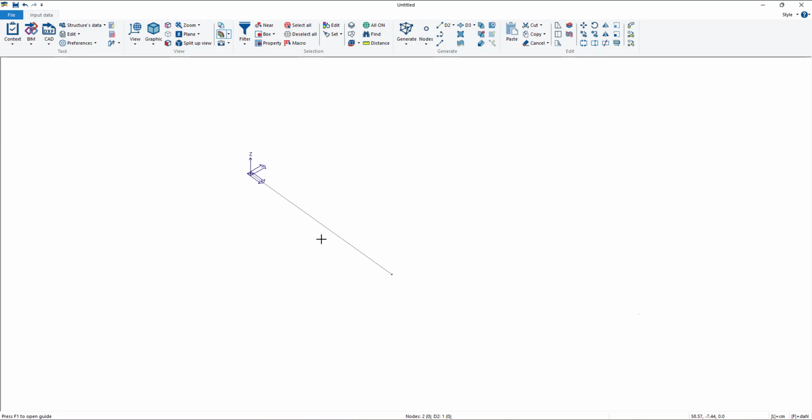Another important thing is that, for example, if I create a node here, now I'm gonna delete this. To select elements, there is the command near. When we click near and it is selected, there is this blue box around the command that is saying us that the command is active. We can click on the element, it becomes red, so an element is selected when it becomes red, and then we can cancel it with the cancel button of your keyboard.